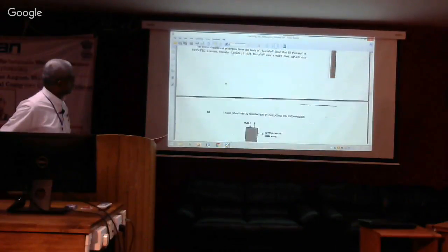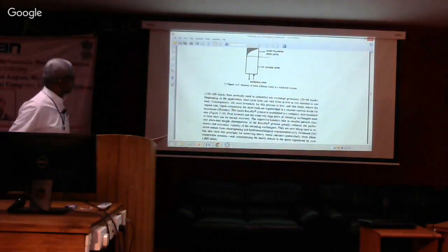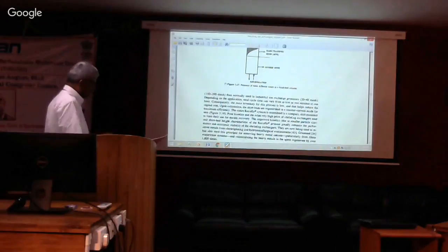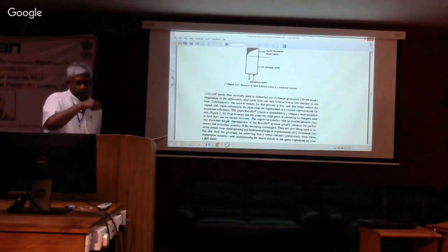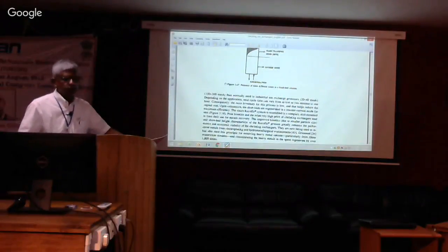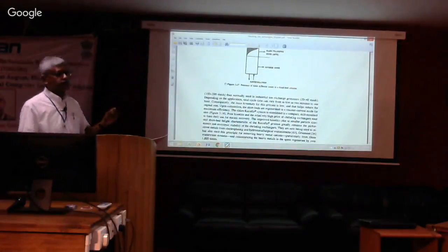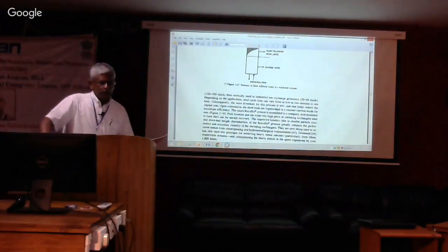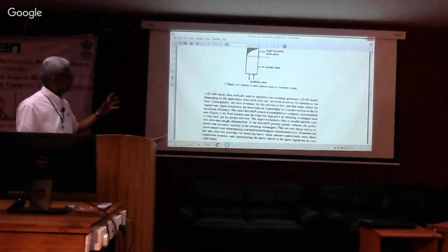And so it's a much finer particle size, typically 100 to 200 mesh, and your flow time is very short, about 2 minutes to 1 hour. When we run typical commercial columns, we run them for days together before they are exhausted. But here, we are running it only for a few minutes. Okay, but it is not a big inconvenience because the process is set up in such a way.